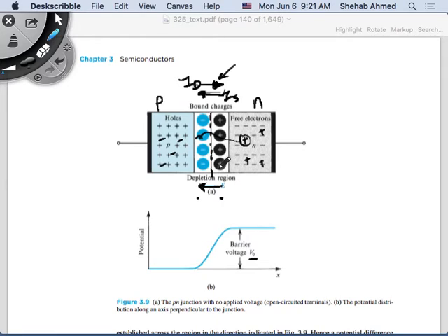What was the source of the free electrons? The donor atoms that had an extra electron. After the electron became free, there was a bound positive charge on the donor atom. This bound positive charge on the donor atom is no longer finding electrons to fill it. Before, in the n-type material, we put donor atoms, fine. Even though the electron became free, another electron from another donor atom maybe filled that hole. Exactly. Right? But now the holes have combined with these free electrons, so I have a region of positive bound charge that has no other free electrons around.